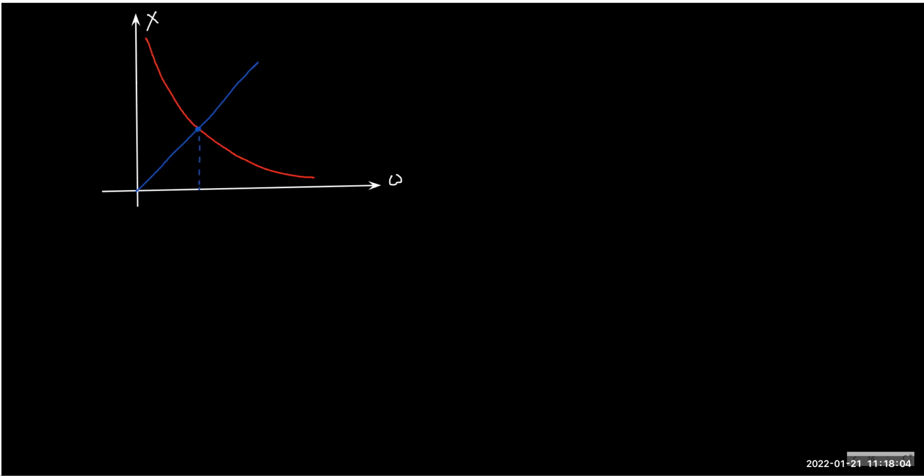So if a circuit is having both present, inductor and capacitor, and if I say this is the critical value, then before this frequency, you can see the opposition of capacitor is dominant, right? So in a circuit where both are present, this will be the dominating factor. But beyond this frequency, the dominating factor is this, correct?